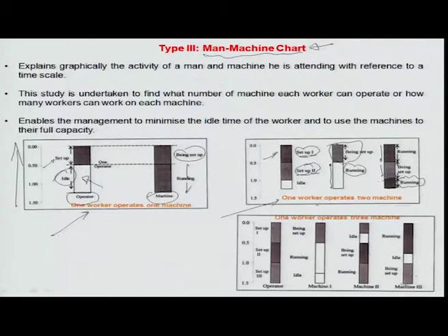And there is a small amount of time overlapping between these two machines where the operator is still idle. So can I actually now load 3 machines on the same operator? This way I can keep on utilizing the operator's time and engage him between multiple machines, so that we don't have any question of overlap time wise between 2 machines. That means setup being done together is avoided.